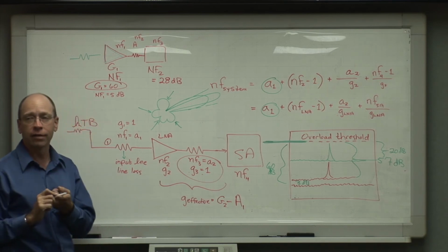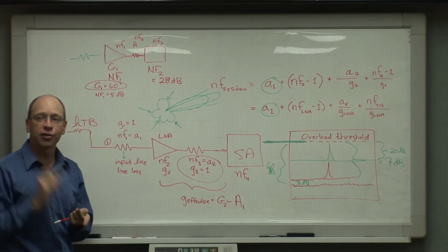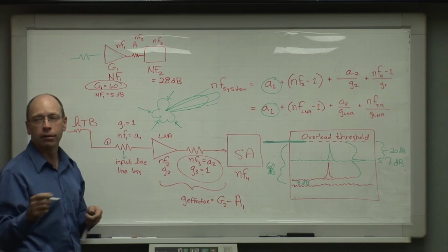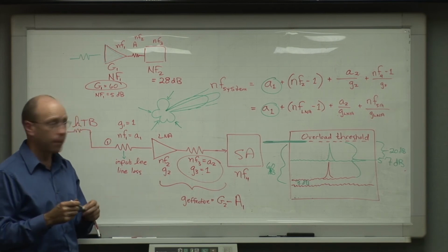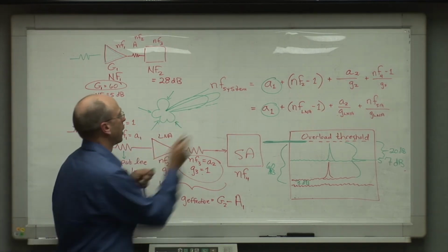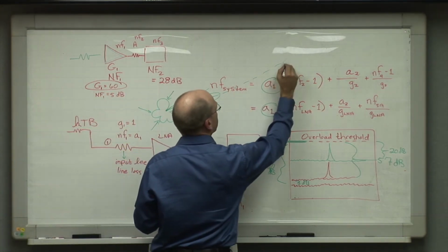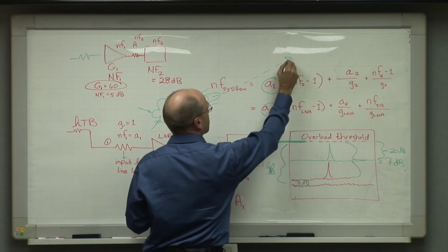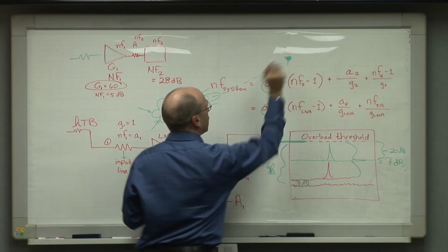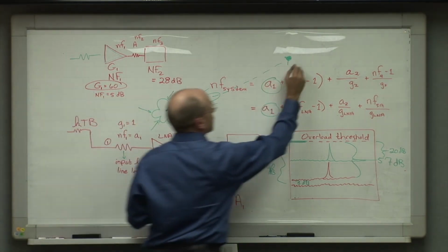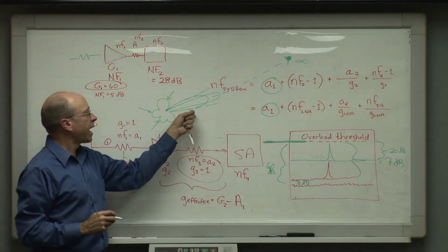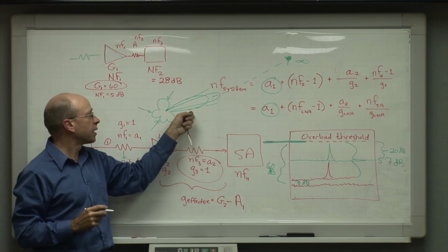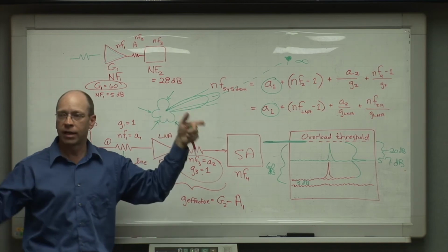However, if I am looking for energy from a discrete source, like say a radio that you may be transmitting with down here in Boulder, then I will get more energy coupled into my measurement system from that discrete source, because it's basically a point source located in effect at an infinite distance. Antenna gain is gain that comes without a cost other than a bigger and heavier antenna.